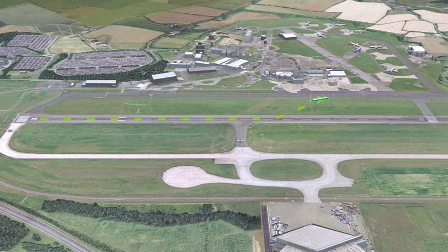A long takeoff distance is considered to be poor performance, whereas a short takeoff is considered to be good performance. However, in commercial transport, the performance is not measured in terms of the takeoff distance, but rather in terms of the weight that can be carried. A good performance, in terms of a commercial flight, would be a takeoff with a large weight, whereas a poor-performing aeroplane would only take off with a small weight. As a general rule, any effect that would cause the aeroplane performance to reduce would cause the aeroplane's takeoff distance to increase and/or to reduce the takeoff weight.